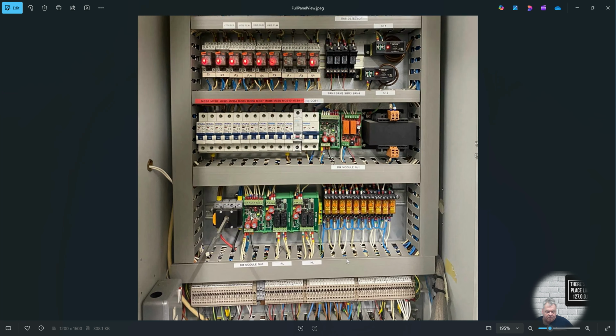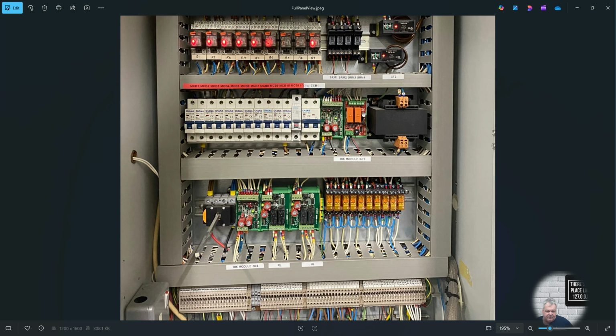And what you do there is you give it an analog signal of 0 to 10, and depending on the jumper settings of these relays, I'll show you a little bit more about these in a minute. You've got raise and lower, so that would be for a valve, and you've got high and low, so that would probably switch a pump on, and then after the pump's running it will switch the boiler on.